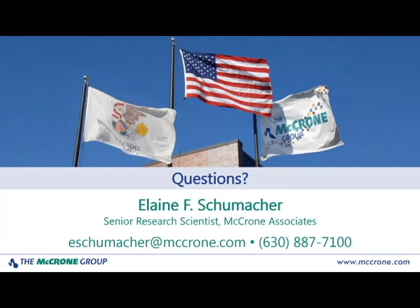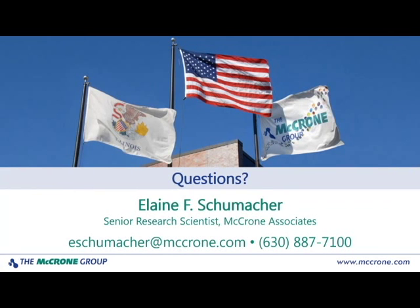TEMs are sensitive, the big ones are high magnification instruments, so environment is a concern. And even with the benchtop model, you have to be careful about probably putting it on an anti-vibration table, having it in an area where you have limited traffic, having a somewhat controlled environment if you can.